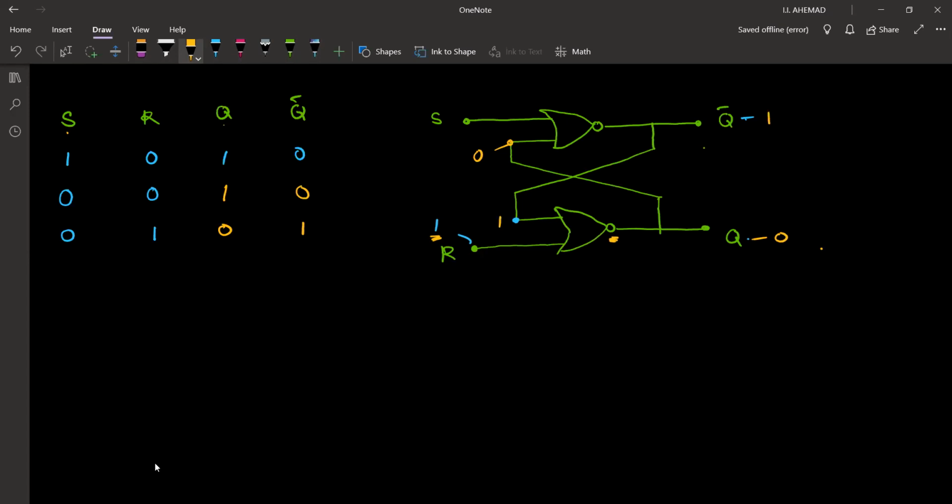Now what we are going to do is remove reset. So this will become 0. This was 1. After removing, it's 0. 1 or 0, that is 1. When it passes the NOT gate, it becomes 0. So this same value remains. 0, 1.